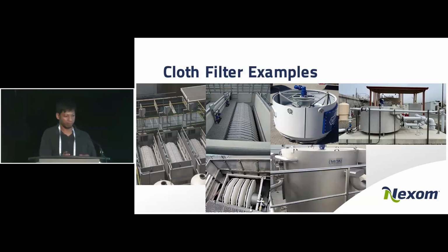Here are some examples of what it looks like. On the left-hand side, you can see a disc filter in a stainless steel tank and in a concrete tank. Usually, it is maintenance-free. Once it starts, we don't have to worry about it. We just have to walk around every day for 10 minutes to check if everything is working. And in case of maintenance, we can just walk on the platform.